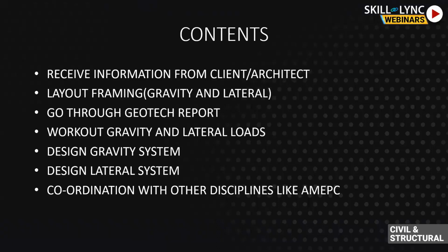First, when you receive your information from clients and architects, you go in and start laying out your framing, gravity and lateral. The information that comes in includes the Geotech report as well. Once you have your framing laid out, you decide what kind of foundations you'll be doing, and then you work out your loads. Then you go into your design, gravity and lateral, and last I'm putting coordination with other disciplines like AMEPC. So these are the bullet points.